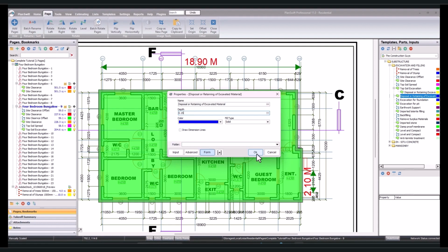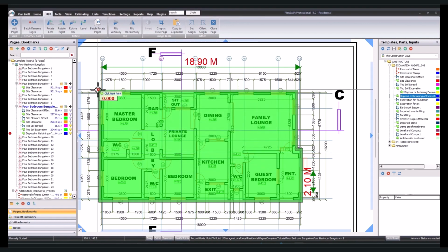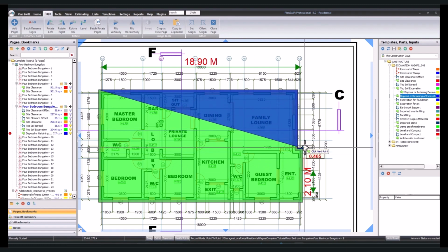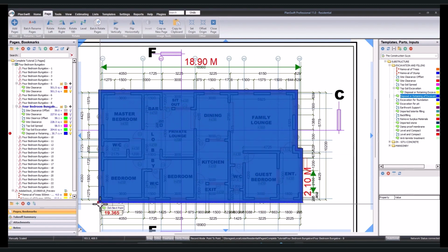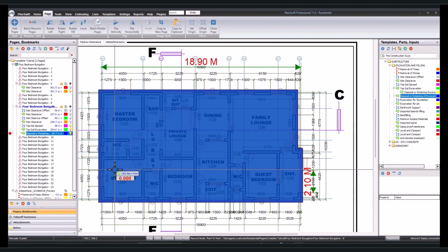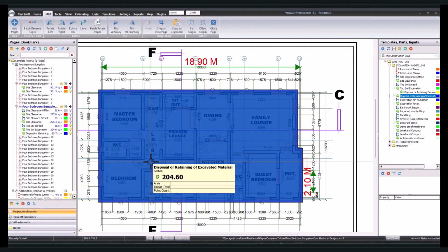So you can either use the metric or imperial method of calibration to calibrate your drawing. You want to have the understanding between the two, so you can use any one. Now I'm using meter. If you remember when I was doing spread, I used millimeter, but now I'm using meter. So I'll press OK. I'll come here, the second point, the third, the fourth, the fifth, and this is the sixth. I'll double click at this point, look for somewhere here and stop. Now we are done with our taking off process.